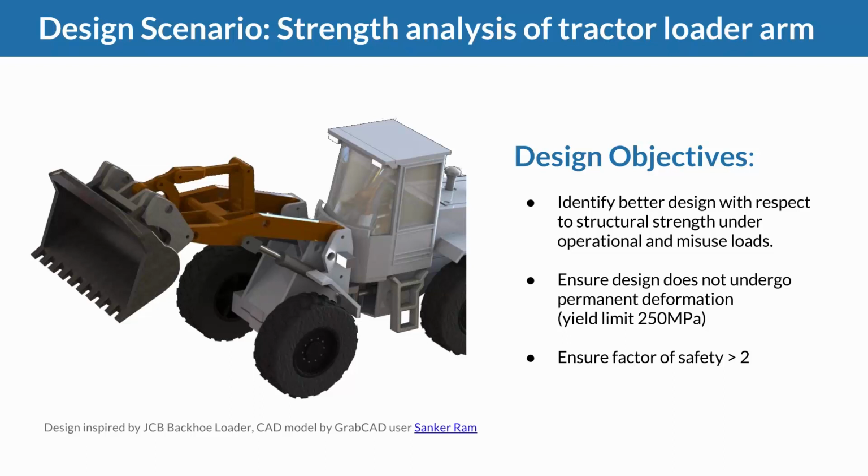Besides these extreme conditions where we consider yielding, so permanent deformation of our structure, one other aspect is usually the endurance or the fatigue lifetime of the component. This structure is made of steel, and there the yield limit and the endurance limit are usually pretty close. So for the example today, we are only considering the yield stress and designing with regards to the yield stress as a reference.